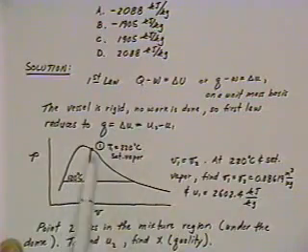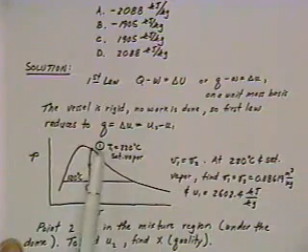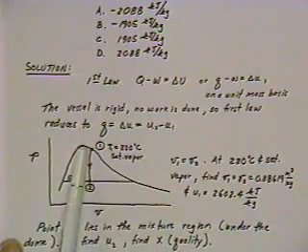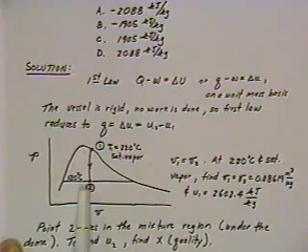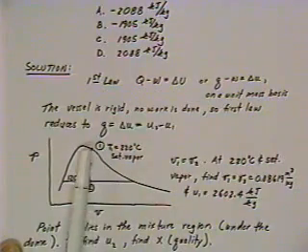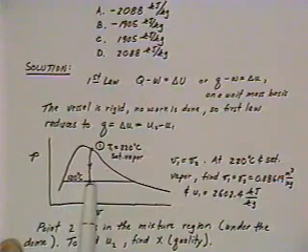If you sketch out the process on the PV diagram, you're going from state 1, which is 220 degrees C saturated vapor, down to state 2, which is at 120 degrees C. Any time you start under saturated vapor conditions and you're cooling off, lowering the temperature, you're going to drop into the mixture region. So point 2 is literally under the dome, in the mixture region.